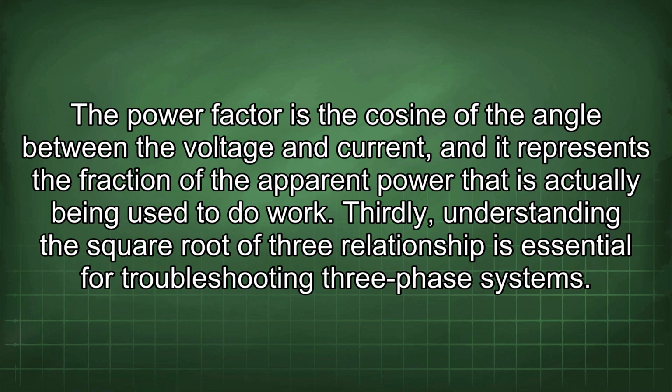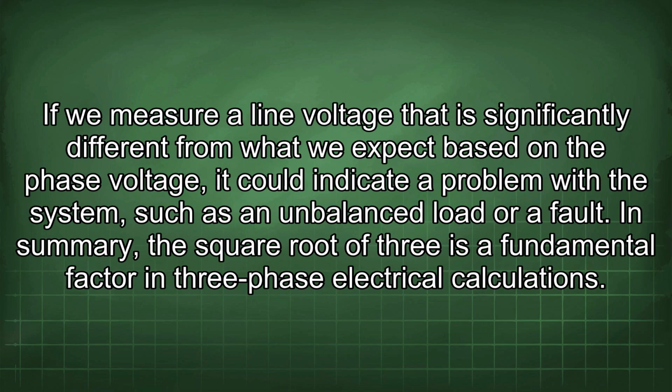Thirdly, understanding the square root of 3 relationship is essential for troubleshooting three-phase systems. If we measure a line voltage that is significantly different from what we expect based on the phase voltage, it could indicate a problem with the system, such as an unbalanced load or a fault.